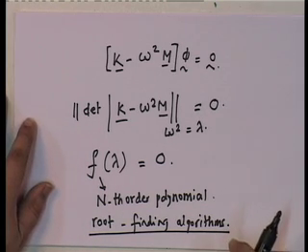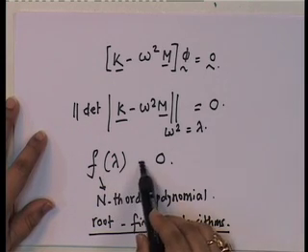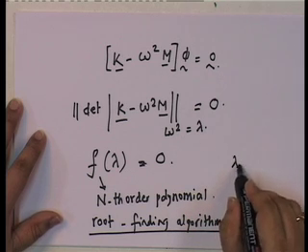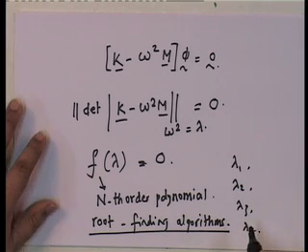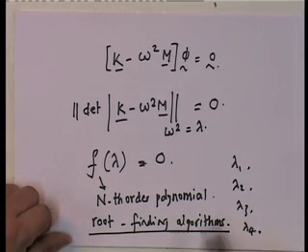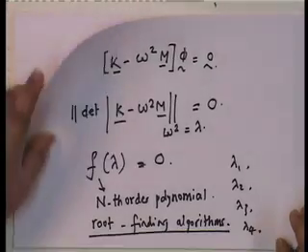And one of the ways of practically finding out frequencies is from doing root finding algorithms, right? And root finding algorithms, there are many. So, you basically have to find out the roots of this function, and from that you get lambda 1, lambda 2, lambda 3, and then there are tests to show how you don't miss any root. Okay. Now, this is something that is done typically in a numerical methods course. So, I am not going to talk about it, excepting for the fact that writing down the polynomial and finding the roots of the polynomial is one procedure for doing practical free vibration analysis.